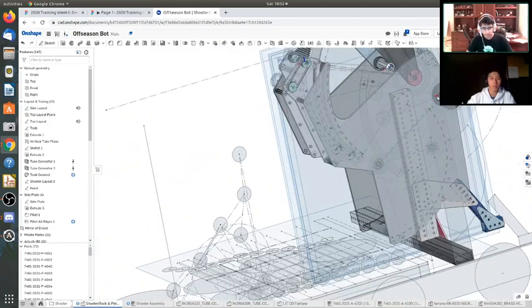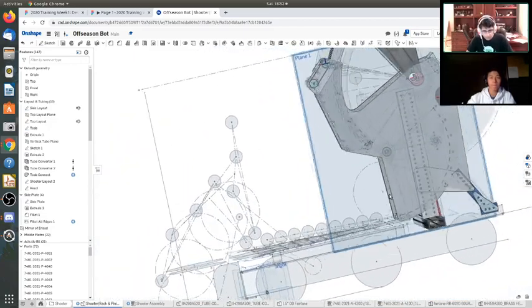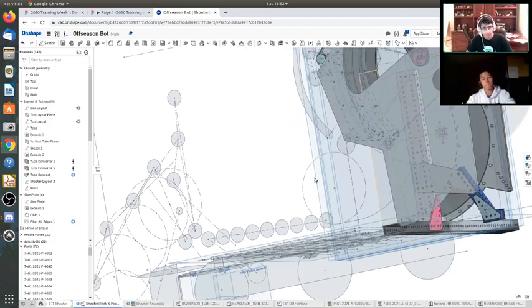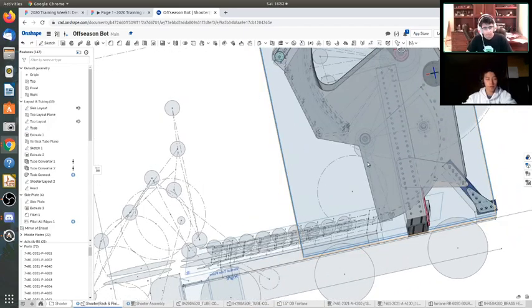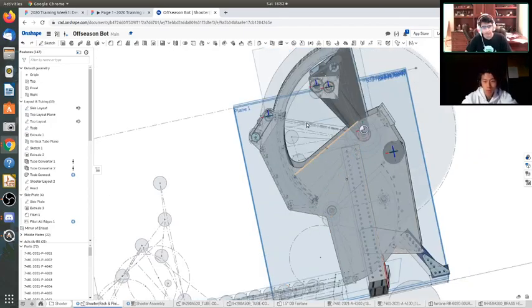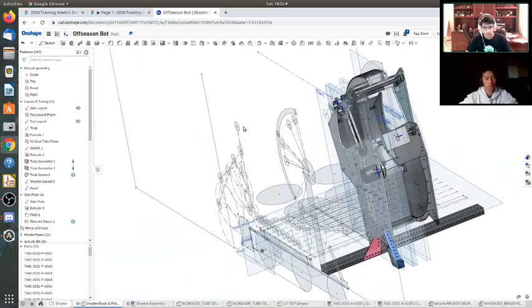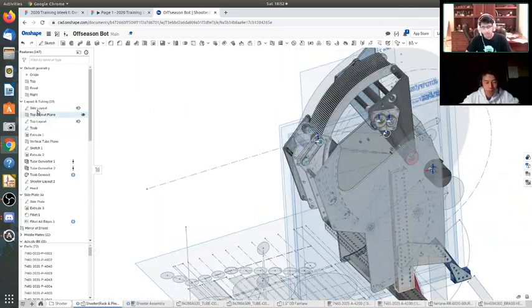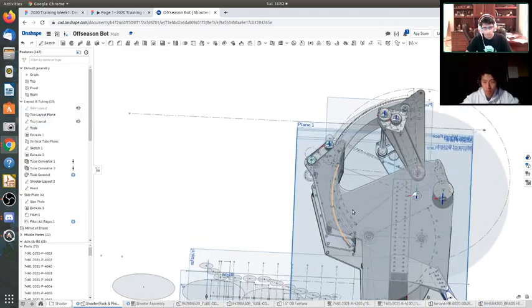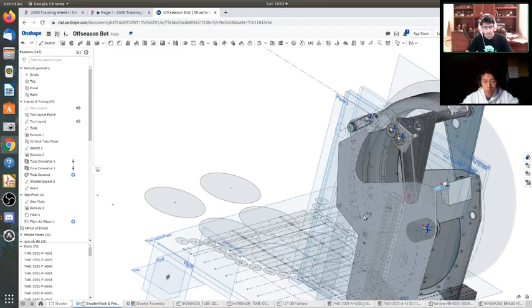What that enables us to do is know where the ball is at the end of the hopper, and from there find the optimal place to put the kicker wheel, and then the path it follows as it goes up through the shooter. Everything's modeled in the sketch. Then you've got more sketches, and from that really detailed sketch, you extrude up your parts.